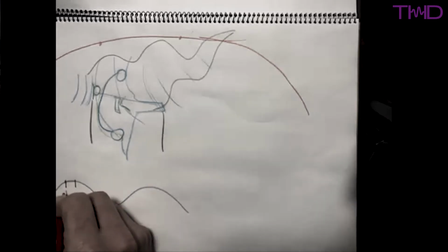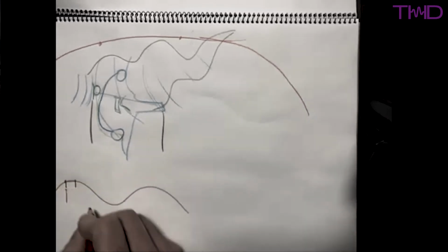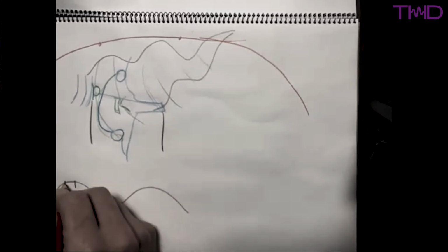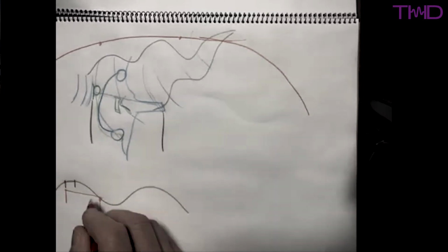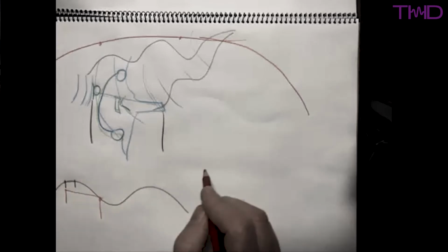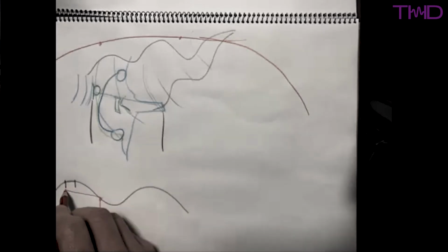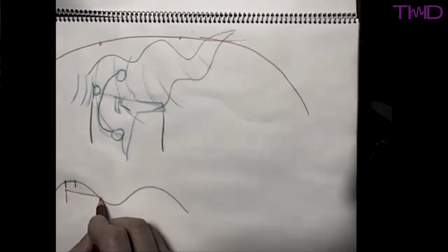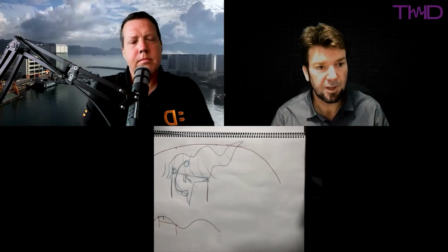But if that distance is larger, say on a large headset, and this is our microphone point, and somewhere way over here is the ear canal, then this is getting to be quite a big distance between the two. I can't be sure that, regardless of where the waveform's coming from, if I just say we'll reduce the magnitude by this amount at this frequency, that would work for one particular waveform arriving from one particular direction, but from another direction, it may be a totally different relationship between those two levels.